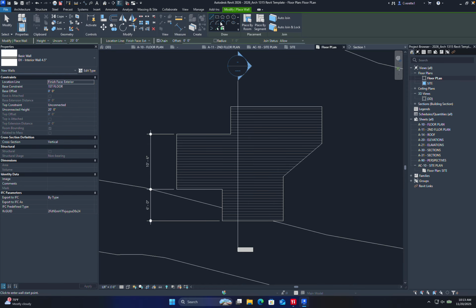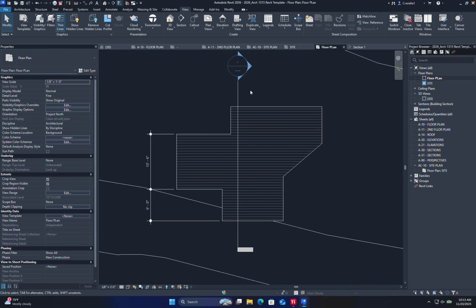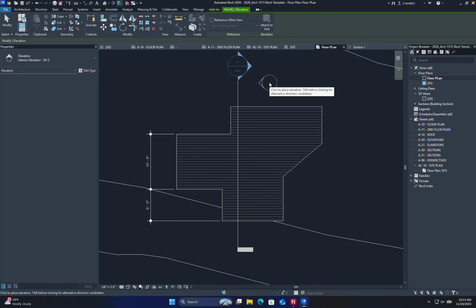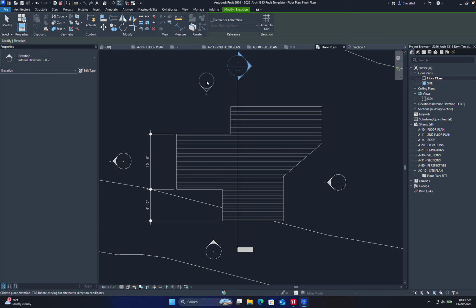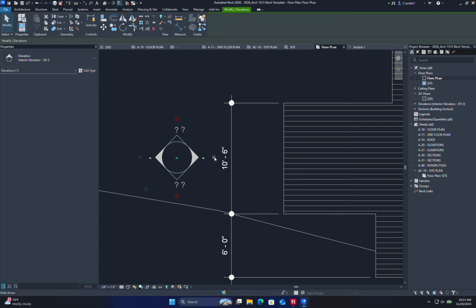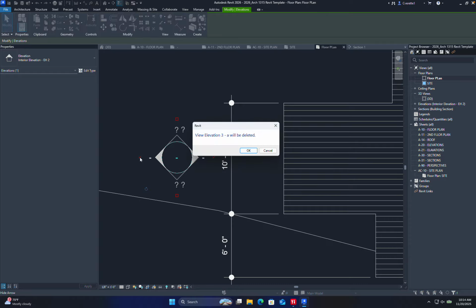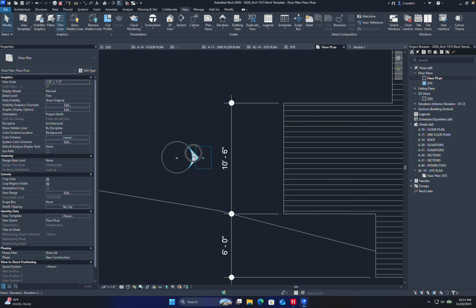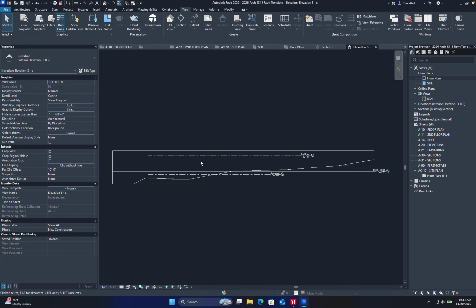However, let's make some walls now that we at least have a section. And my bad, let's get some elevations in there. You'll see by default, it actually kind of helps you pick the right view. Sometimes you've got to get a little bit closer to the model, and it's okay if it doesn't work sometimes. If it accidentally faces the other way, it's okay. If you click on it, you can check that box and uncheck that one. It's going to ask, are you sure you want to delete that? Yes, please do. Because when I double click on this one, bam, elevation view.